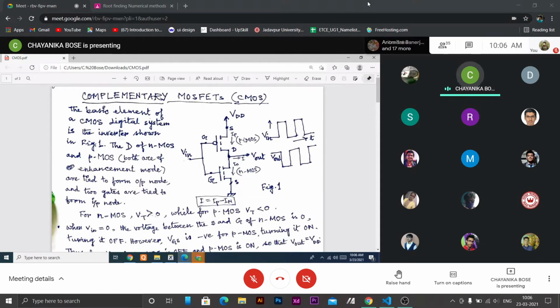So for PMOS, your drain voltage, drain current, gate voltage, everything will have voltage of opposite polarity, current of opposite direction with respect to an NMOS. So if a pair of PMOS and NMOS are connected in this way, so that this pair of MOS have exactly similar properties, but complementary because everything is opposite for these two MOS.